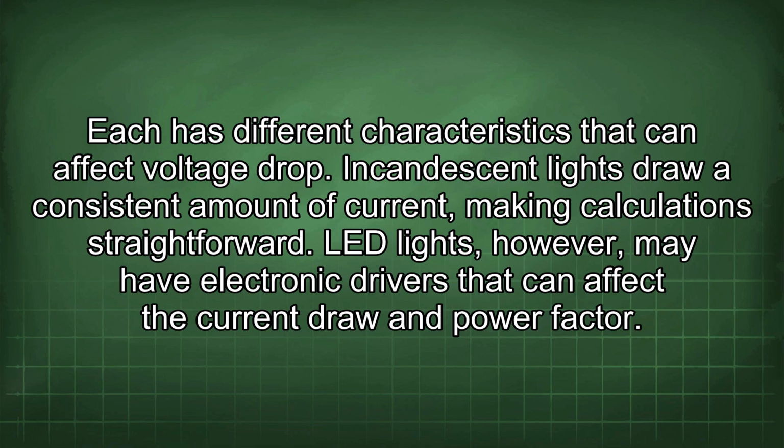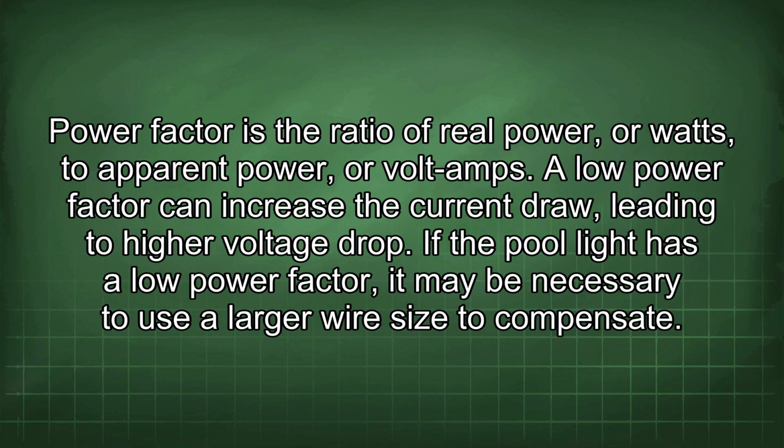LED lights, however, may have electronic drivers that can affect the current draw and power factor. Power factor is the ratio of real power, or watts, to apparent power, or volt amps. A low power factor can increase the current draw, leading to higher voltage drop.